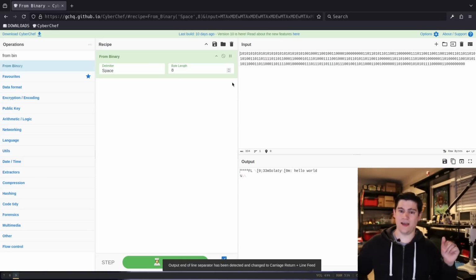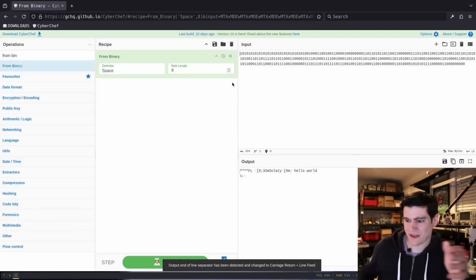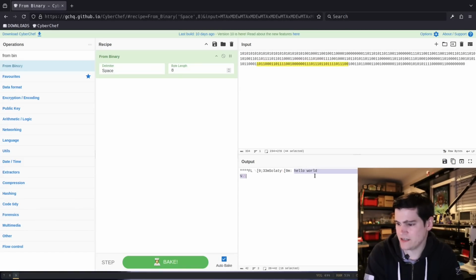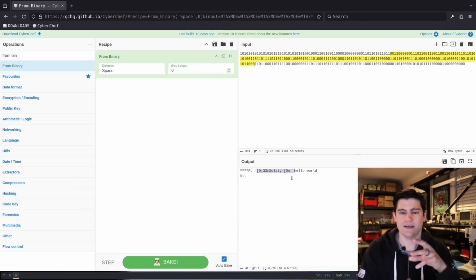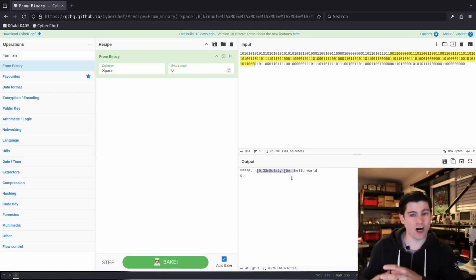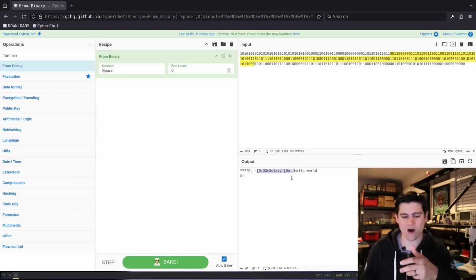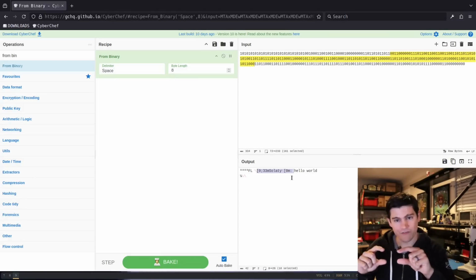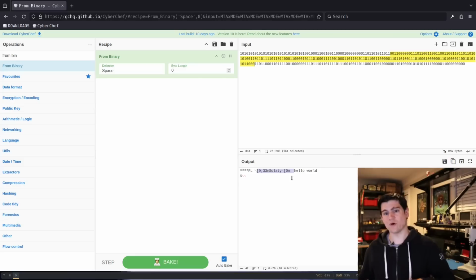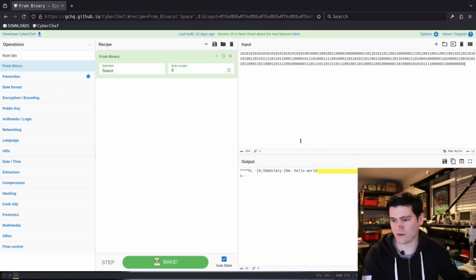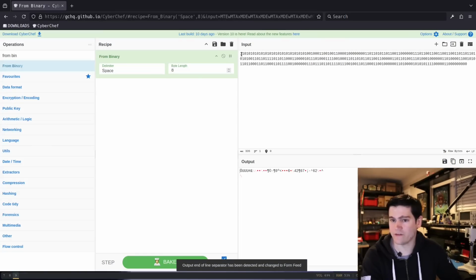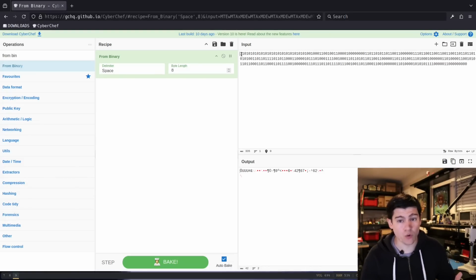So I hit that, and okay, I removed that first bit. Now all of a sudden we can see our hello world message. We can see the name of my Flipper, right? And if you're familiar, these are Unix terminal color codes. That's how it's actually transmitting the color of the terminal text and what it should be. So our original message that had that 1 in front of it is probably just some kind of a start bit, or we just need to ignore that.